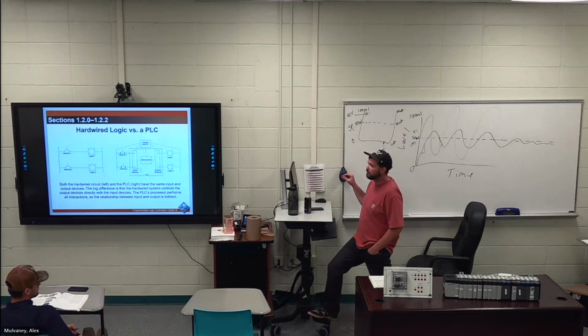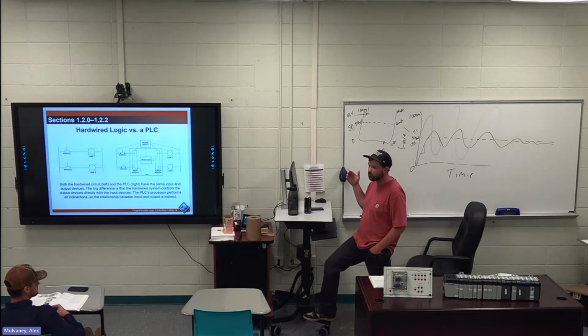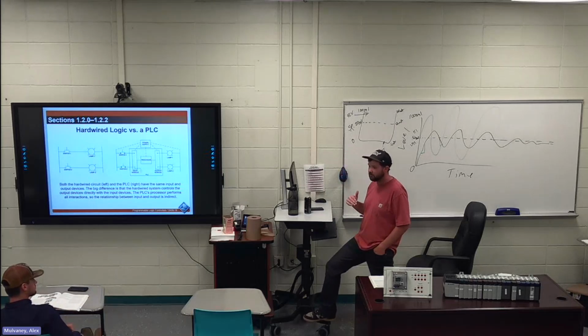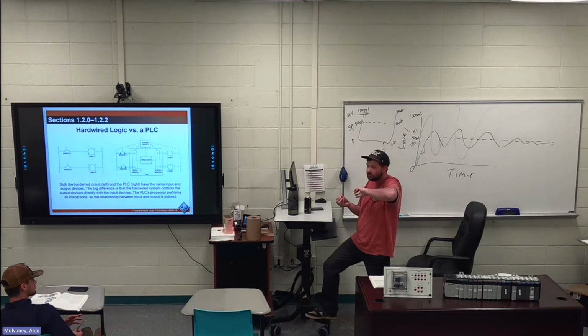So what I would have done is there's a way to search in the programming, like go see what he's forcing open and close, and you take that bit and you can search everywhere that bit is used in the program and see what's either telling it not to be turned on or like going over. Kind of the way it works is like if it's written before, it will override that function, and you can go see whether it's being told to turn on or off.